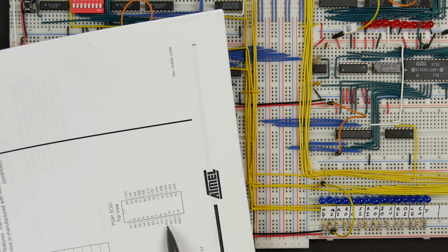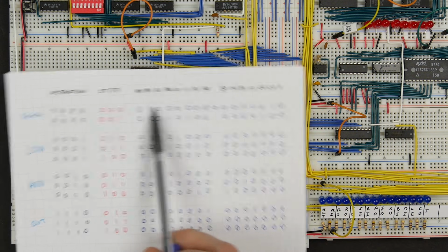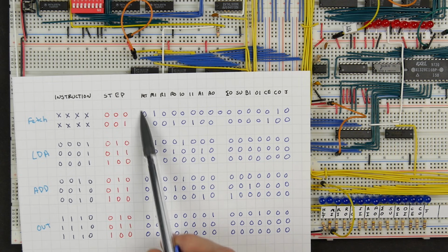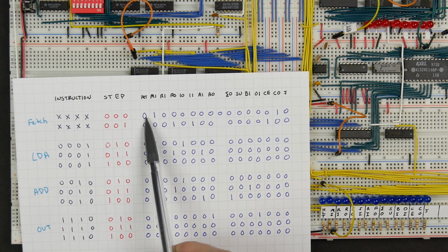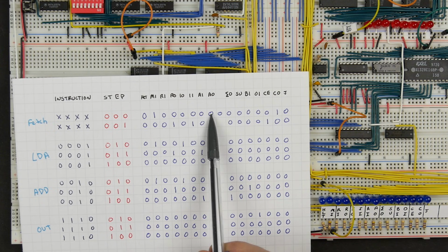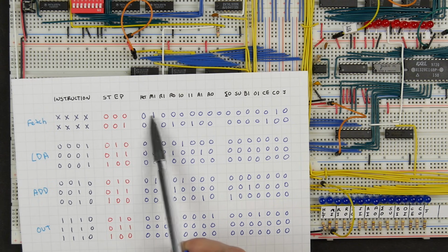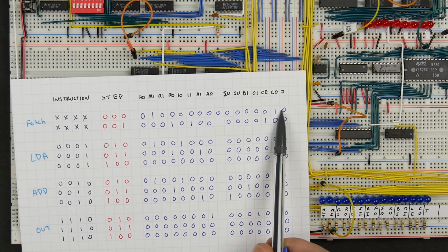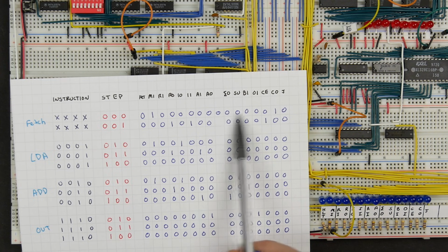And the way I want to do that is, I've got I/O 0 through 7. To make things easy, I want to line it up in the same order that it is here, so the chip on the left will be these 8 bits on the left, and the chip on the right will be these 8 bits on the right. The bit on the right here will be I/O 0, and I/O 1, 2, 3, 4, 5, 6, 7, and then over here this will actually be I/O 1. We won't use 0. 1, 2, 3, 4, 5, 6, 7 will be the sum out. Just to keep things in order.